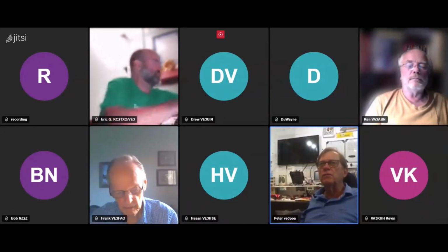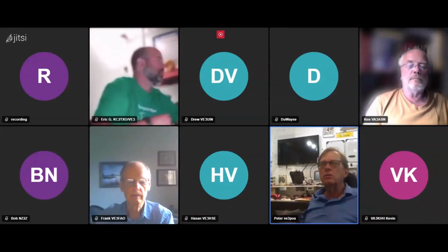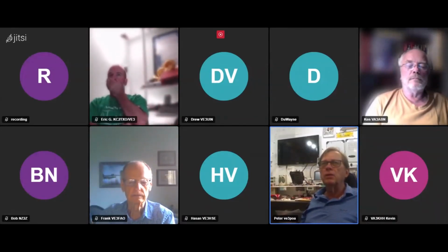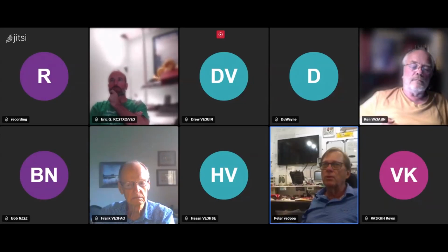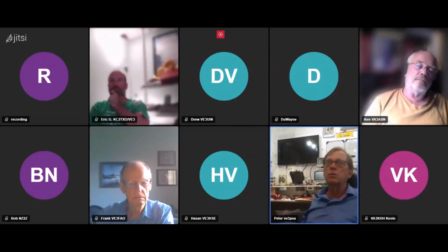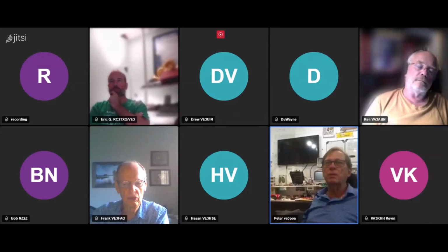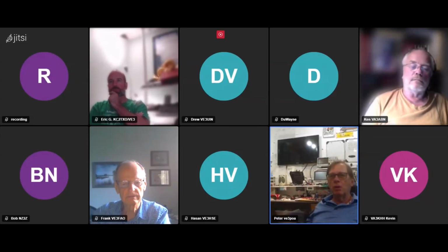I think the issue is the first mixer is showing the output is way down. It's about 30 dB down, whereas on the proof of concept board I get about an 8 dB gain. So there's something going on there. Now, what is it? I don't know, because next in the chain is a transformer, and that transformer is fine, or it was. And that's the other thing: the Phoenix board worked before I took it to Dayton, so it sort of sounds like the signal's grounding out. But I've changed the mixer, and that didn't make any difference. Anyway, I'm confident now that that's where the problem lies.